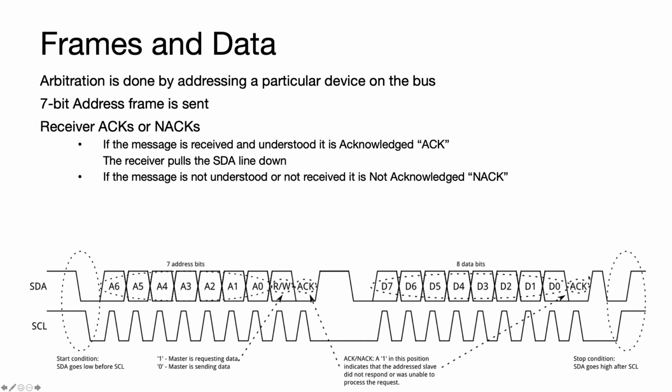Now, what's tricky and confusing about NACKs is if you have nothing on your peripheral bus. You didn't even solder anything on there, and you tell your controller to go out there and send to this address, you're going to get a NACK. No worries, you will get that NACK. Why? Because a NACK is just the peripheral not pulling it low. So sometimes you can confuse yourself by saying, oh, there should be a NACK there when the peripheral's not on. So getting that ACK is always a really nice sign of life, because the peripheral is actually on, trying to do something for you. All right.